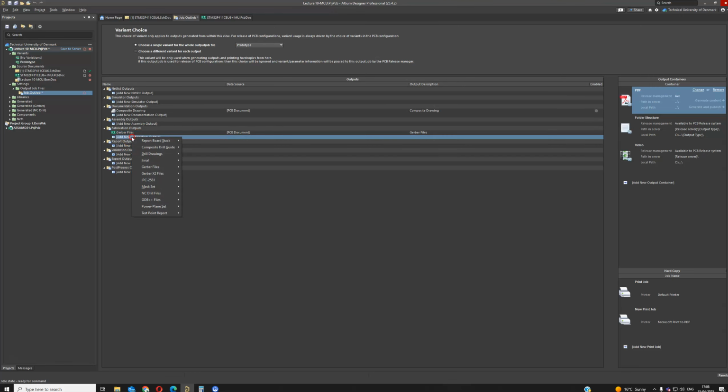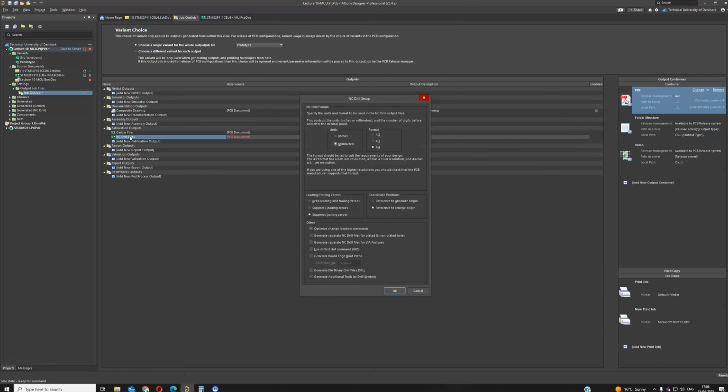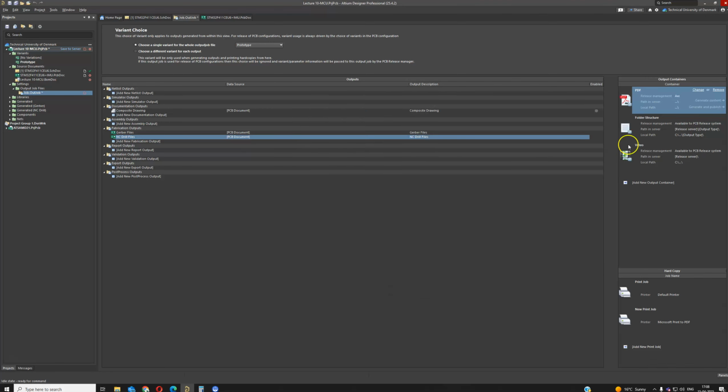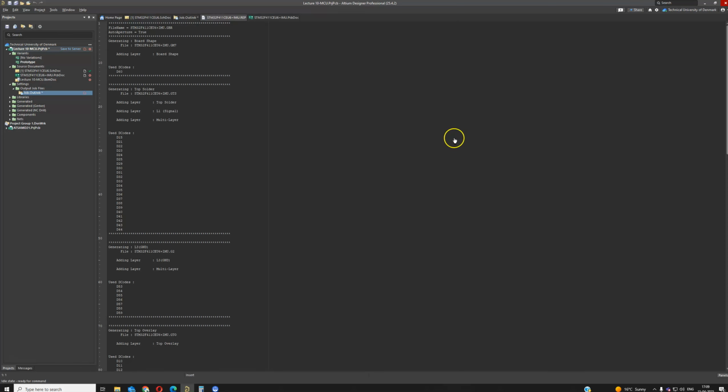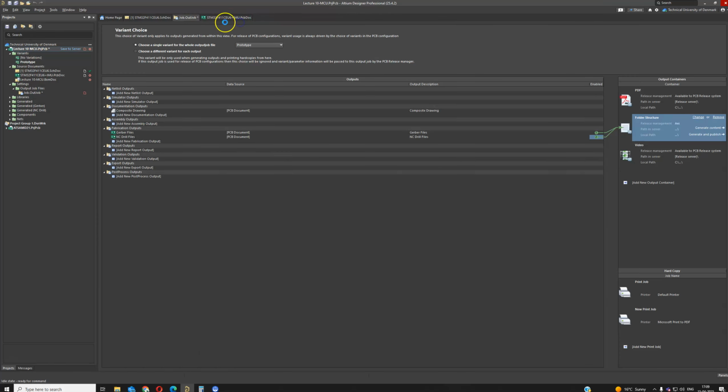and then we need the drills. So with this file, the manufacturer will know all your holes, vias, holes, diameter. So all this parameter of holes and vias, it will be here as well. So basically, yeah, you just keep it default and okay. Then folder here, so we want to generate both. Generate. Then we close this. We close this.